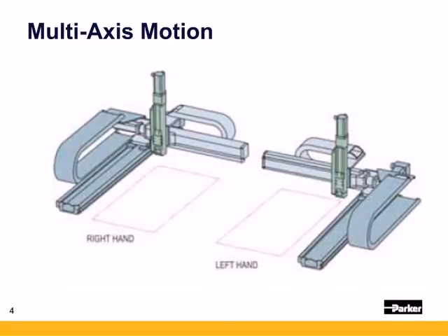Here is a different type of machine with two 3-axis linear positioners. These 3-axis XYZ systems could be linear or rotary servo, or stepper-driven in any combination. For interpolated motion, each system would have its own coordinate system. So the right-hand system would be on one master and the left-hand system on a separate master. Each system could be running its own type of multi-axis motion.